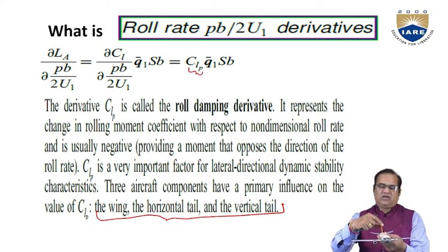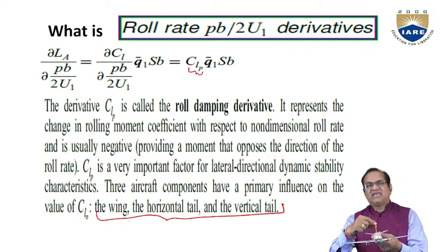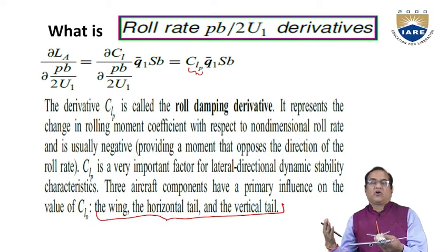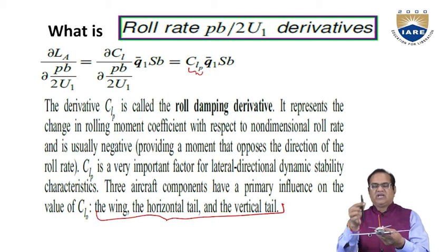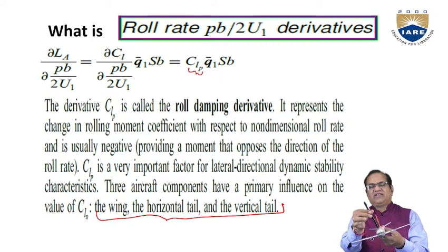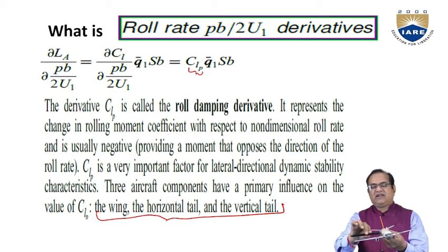But how is this vertical fin making the aircraft roll stable, or laterally and directionally statically stable? Just, the aircraft is flying like this with this much lift. You have rolled this aircraft. The net vector of this lift is also turned and there is a force. One component of the force, the horizontal one, will act in this direction.